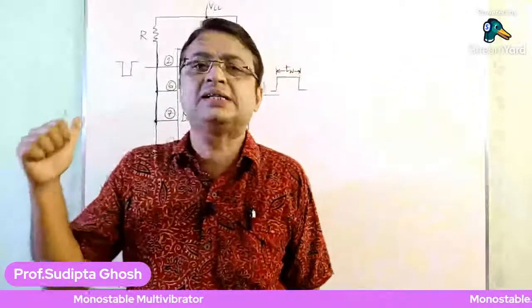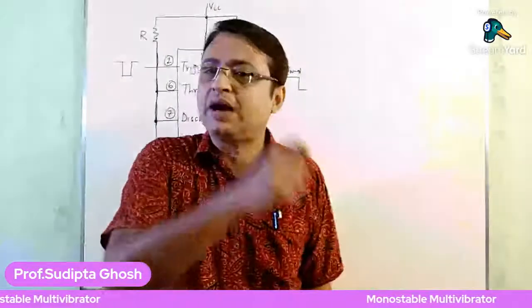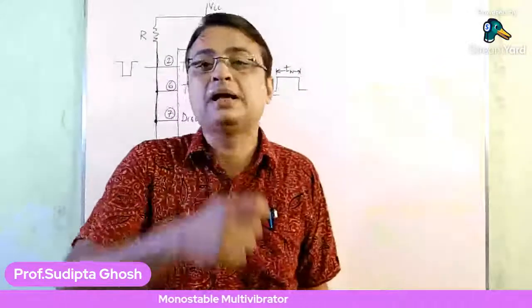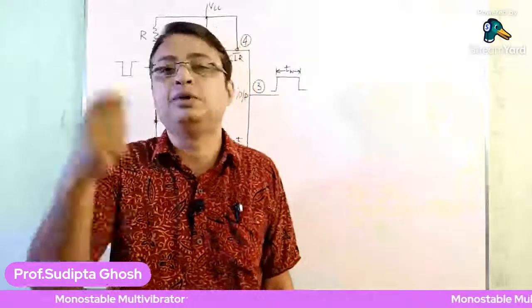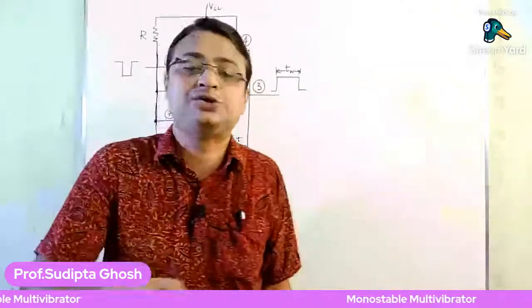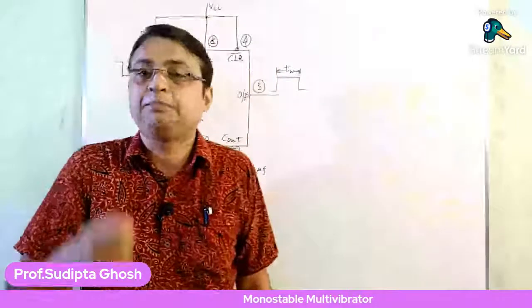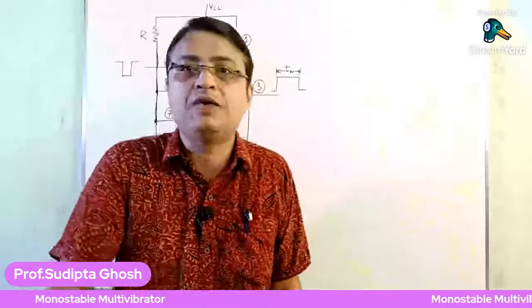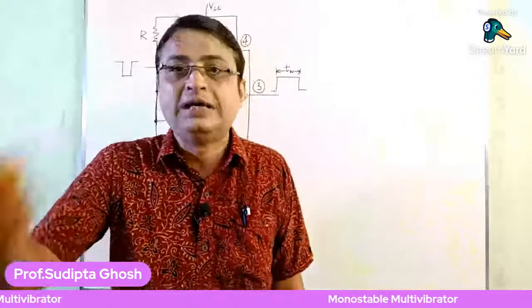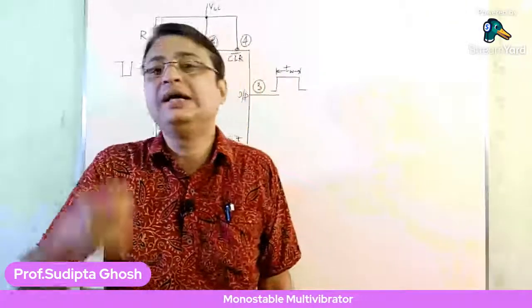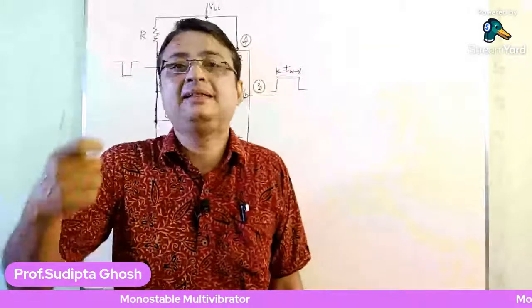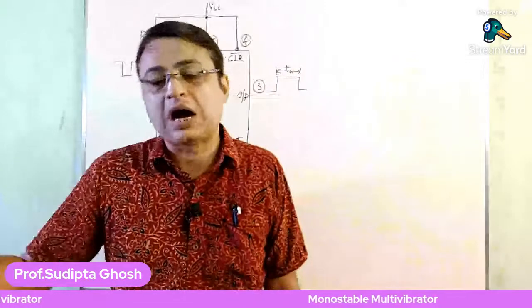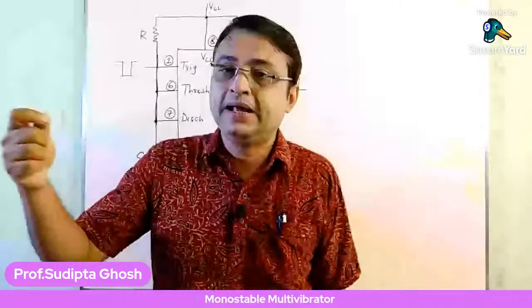We already discussed in our last lecture that when the threshold comparator goes high, it will make a high at the R input of the RS flip-flop, which actually resets the flip-flop. That means the Q value of the flip-flop goes low. That means the Q bar value is equal to 1, and after crossing the output buffer, it will be at 0 value.